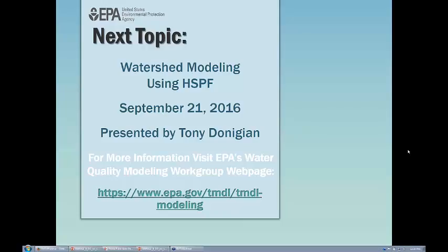Well, I thought I kind of answered that. It's very, very difficult to do. I did some work on the Neuse River estuary in North Carolina, and they have a pretty healthy zooplankton population there. I couldn't explicitly simulate them as a state variable. I did include them in my model by providing a time function and a grazing rate for when they were typically in the area. But typically, the effects of zooplankton are calibrated into the death rate, like I said previously.